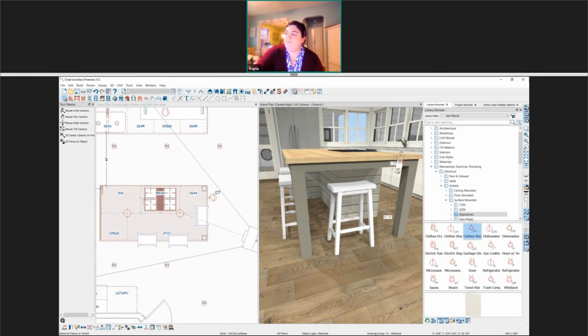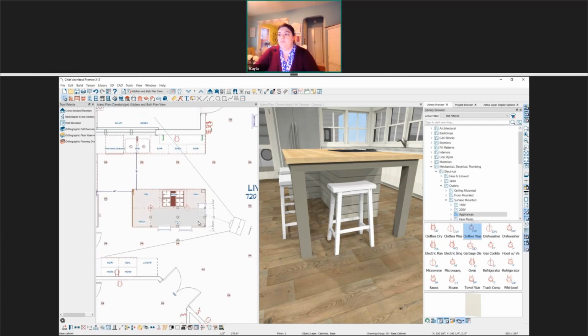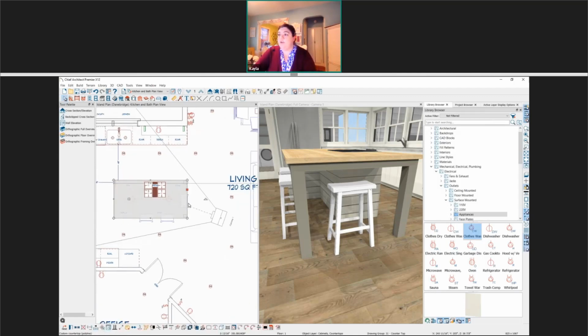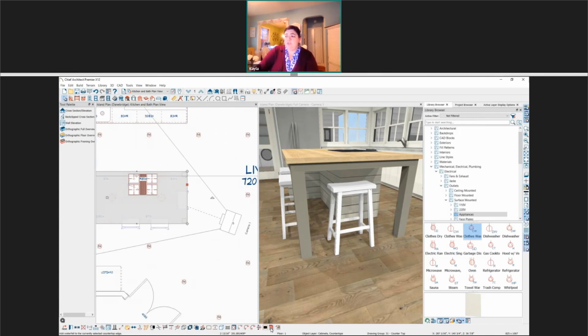Of course. Kayla, we had someone write in and ask if you could demonstrate one more time how to make the waterfall countertop show. Absolutely. Thank you. So I'm going to go ahead and convert this, because I do have a custom countertop here. If I select any edge of a countertop, down in the edit toolbar I have add waterfall to selected edge. So that's one way we can do it.